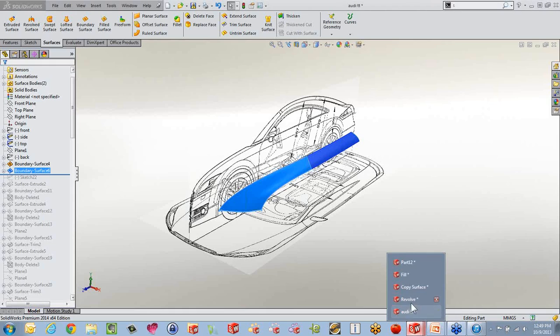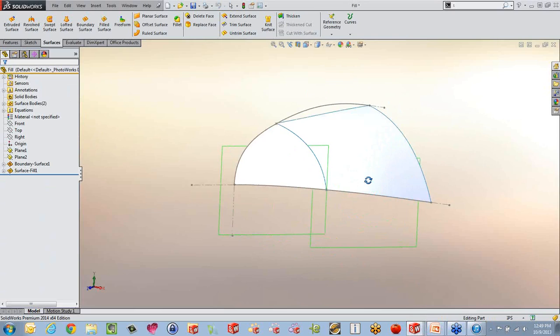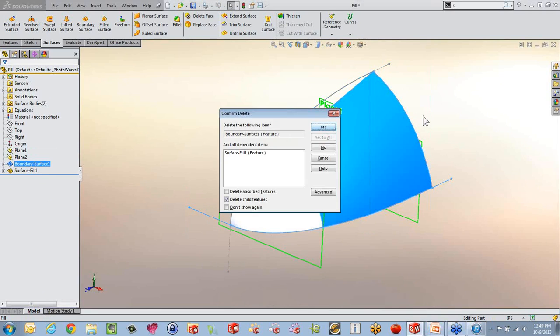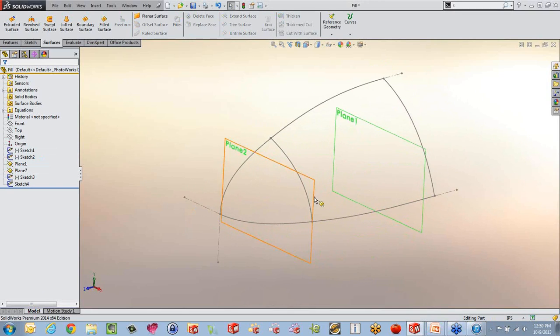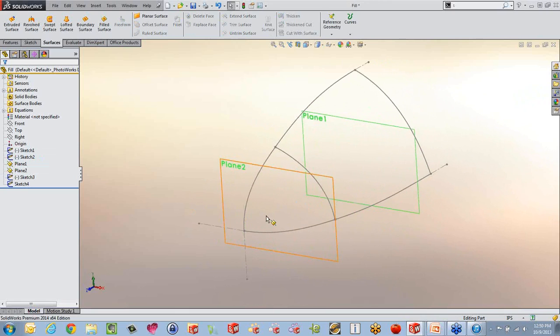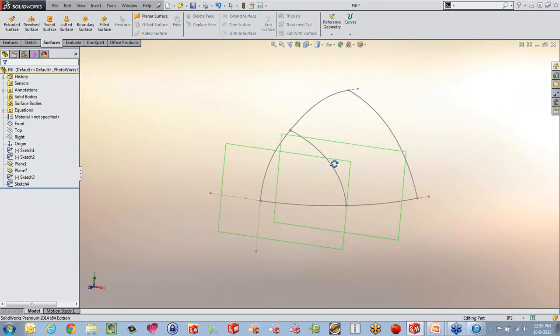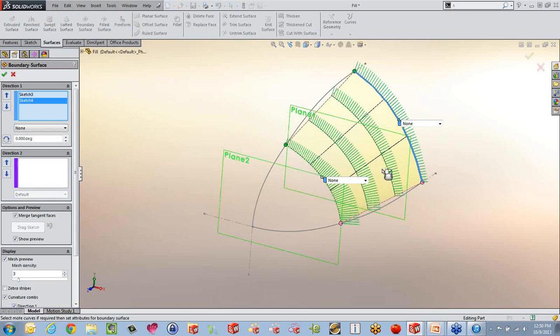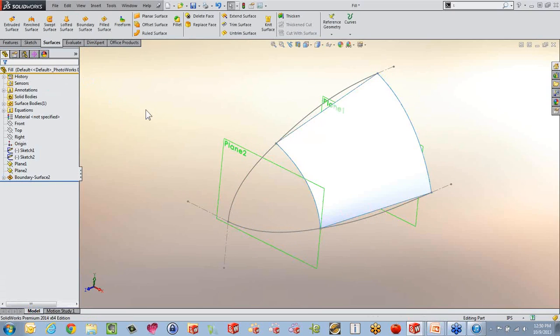So again, if you go back and look at something like our surfaces here, if you start playing around with surfacing and you want to do some swoopy surfaces, you can build up these guides, this shell, almost like a boat hull or something like that, and then you can start using these different tools to drive your surfaces through here. So I hope that this was a good entryway into the surfacing tools, and walked you through some of the different ones.